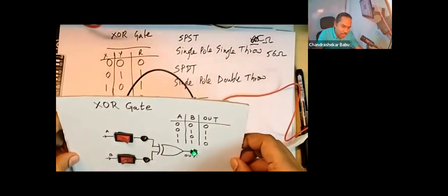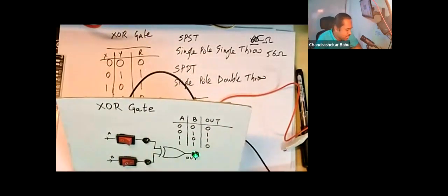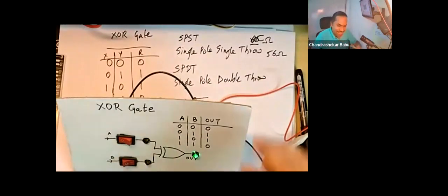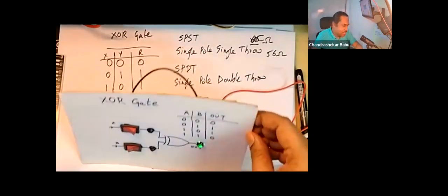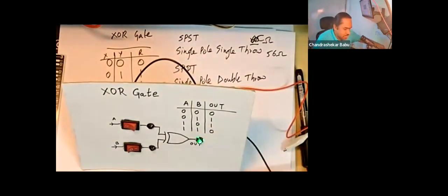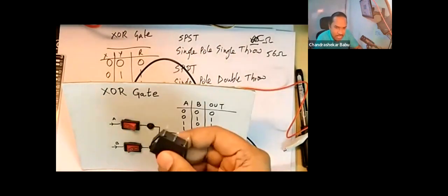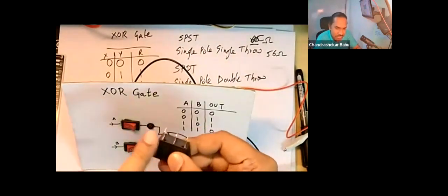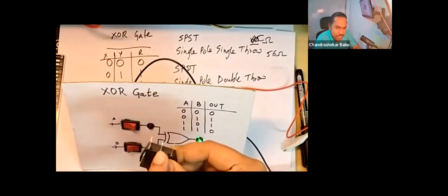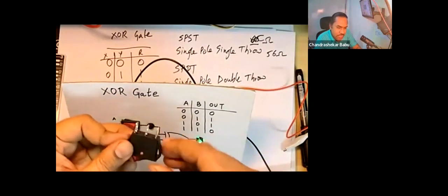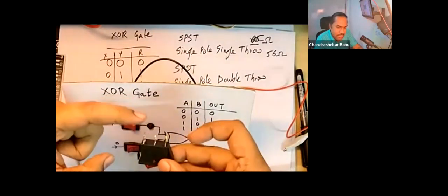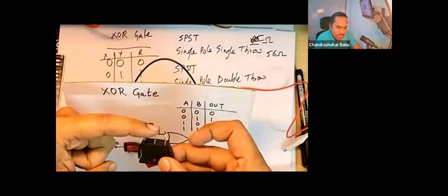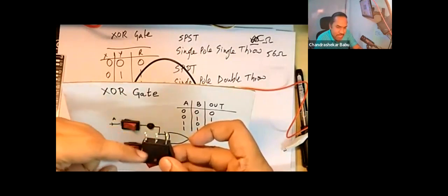This is actually called an XOR gate. Technically, it stands for exclusive OR, but it's also called XOR for one more reason. If I show you the circuit behind, you will see why it is called XOR. These switches I showed yesterday are switches with 3 pins, not just 2. There's a common pin, and there are 2 sides here. So when the switch is in one position, it creates a connection between these 2 pins.